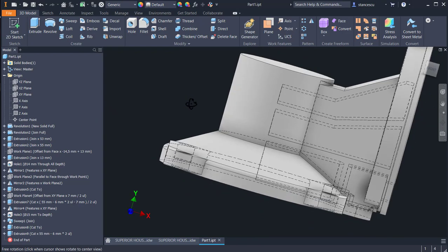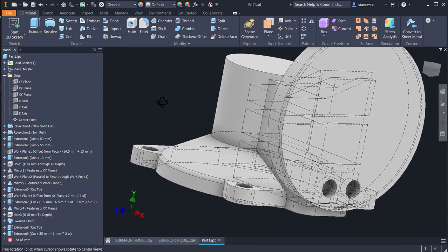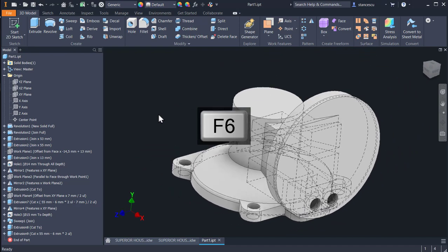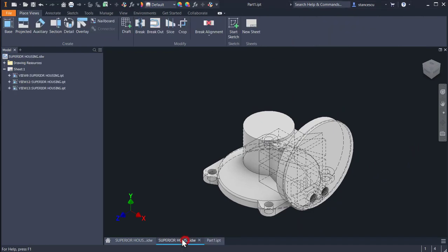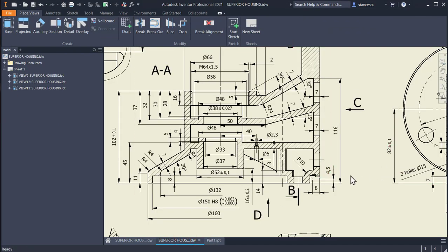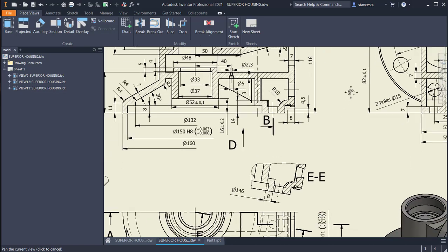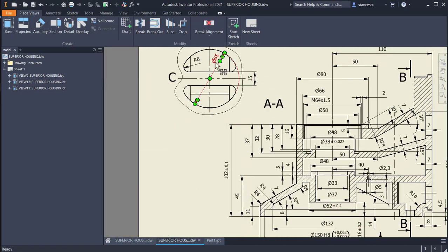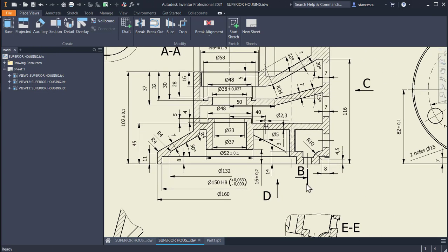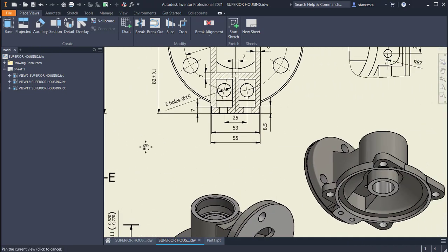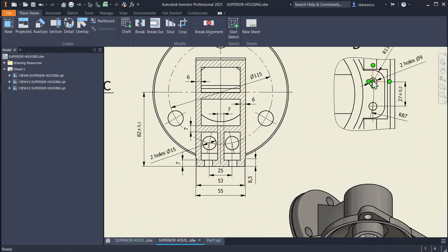Now, as you can see, they are inside. Good. Now we create some orifices to look inside. One is this, diameter of 65, 15, radius 6, and the others are these two in the bottom, centered of the arcs of 9.